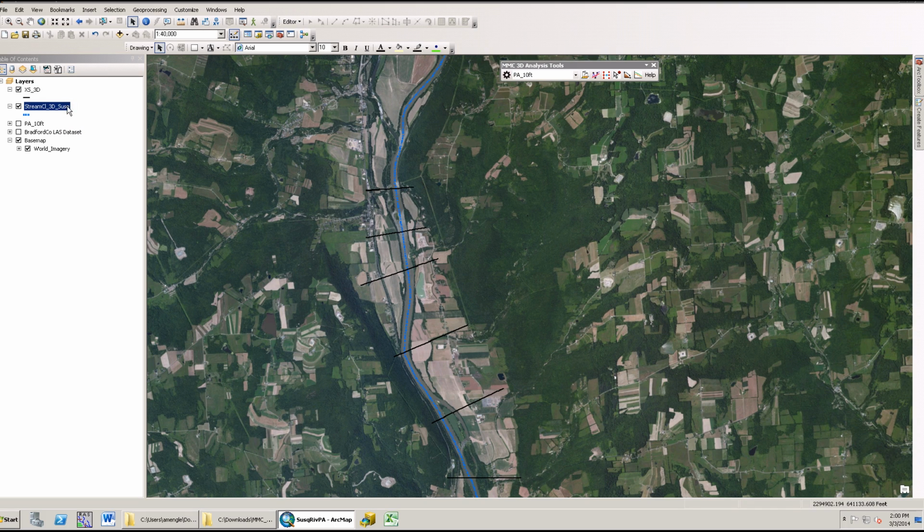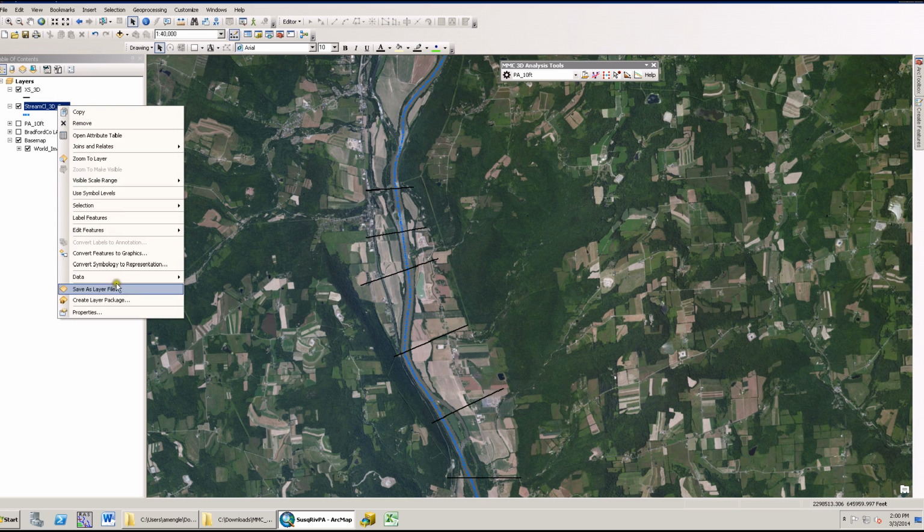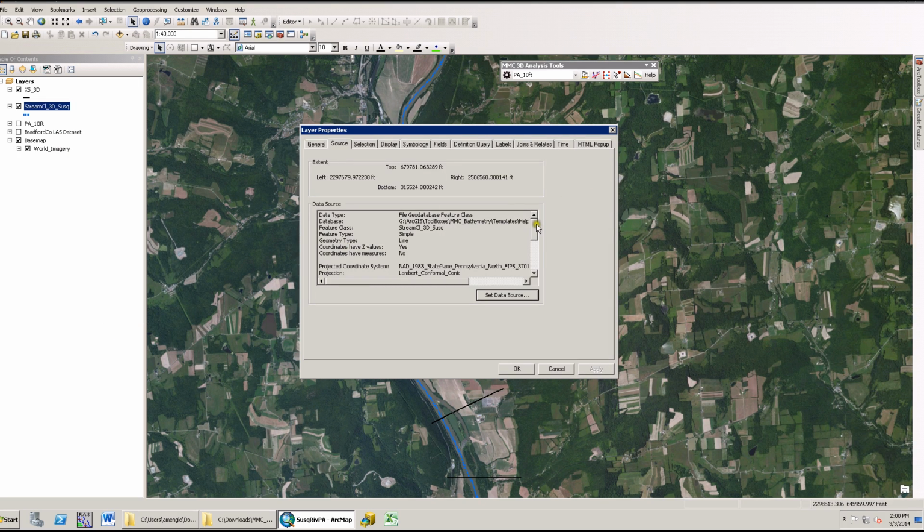This tool is to be used to understand what vertical and horizontal tolerances are reasonable for the data the user has. If there is a 3D line layer in the current map document and the user is not in an ArcMap editing session, the Weed 3D line tool will be active to use. Additionally, in order for this tool to work, the map data frame and 3D line layer must have a coordinate system defined with vertical and horizontal units in US feet.